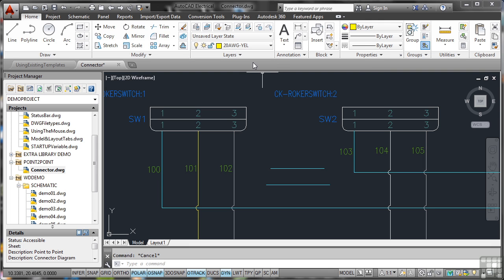So if you've got a whole load of objects that are on the 0 layer, the default layer, but you want to update them to a particular layer, use Match Properties. Find one of the existing colors that you need, use that as your source object, and then the destination objects are the ones on the 0 layer that you want to convert to the new layer. So there's lots of tools in there with layers that you can use, and as we work through this course, if there's anything about layers you need to know, I will make sure that I tell you.